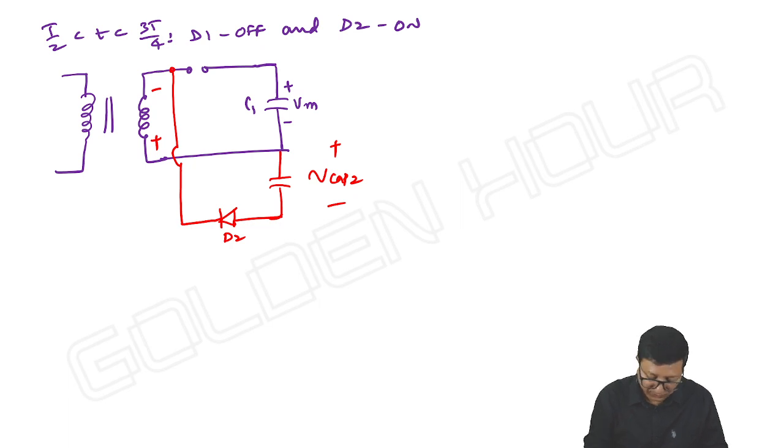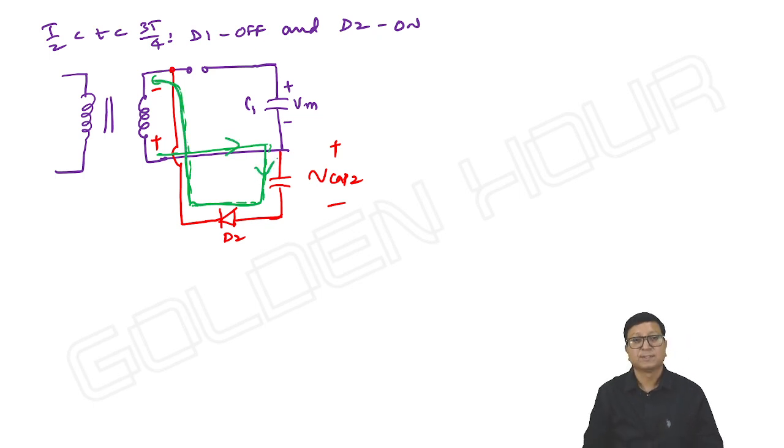Current flows from the positive to the negative terminal of the supply. So here the current starts at the positive terminal, comes down and flows through the diode D2, and finally goes to the negative terminal. So current is flowing in this direction, downward. Even though Vs is negative, the current direction is downward, so the capacitor C2 will charge with polarities plus, minus. Is it not so?